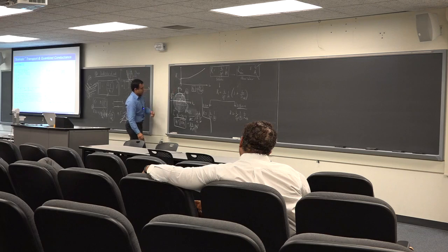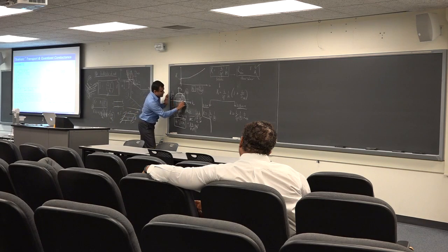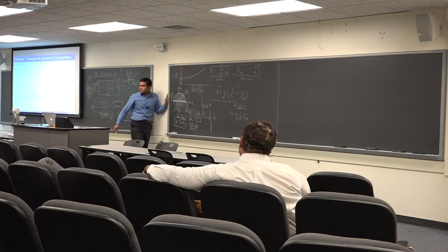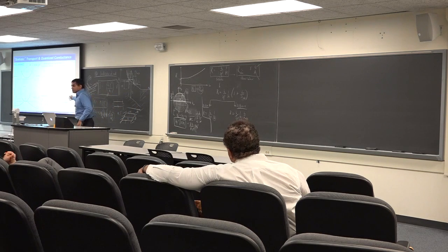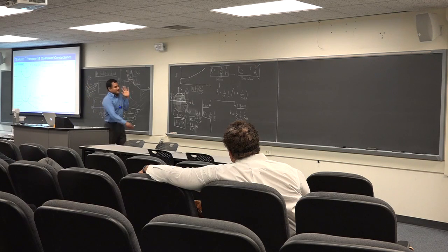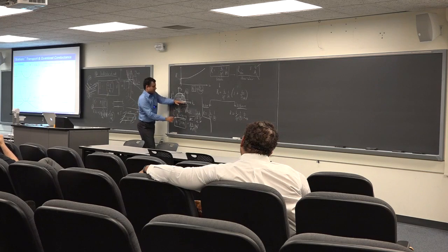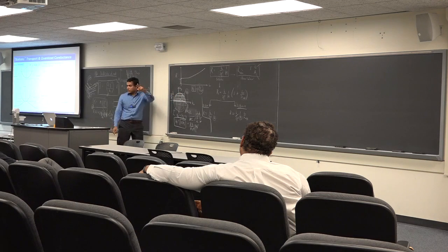Electrons are going that way, right? From source to drain. So you can now think of this picture as many 1D channels. Here's a 1D channel. We have already calculated the 1D channel conductance is 2q squared by h for one mode. Does that make sense? For one mode. And when I'm saying that, if I look at just this mode and forget about everything else, that's a 1D mode. Right? And you can now start seeing that if I look at this layer, all these slices are effectively like 1D modes. Right? They look like 1D modes.